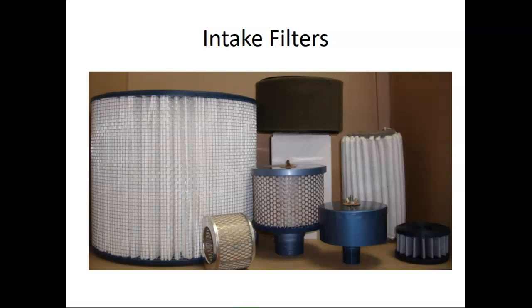Filters are something you want to be very aware of, because if you've ever seen the air filter in your house and it gets nasty after what, a month or 3 months, that's where you might want to pay more attention to the filter on your compressor. Why? Because that thing's probably even nastier. Because we generally don't keep those in the house where we try and be very clean and not as dirty. It's out in a dirty, nasty shop all day, sucking in nasty dirt. Might want to change that a little more frequently.